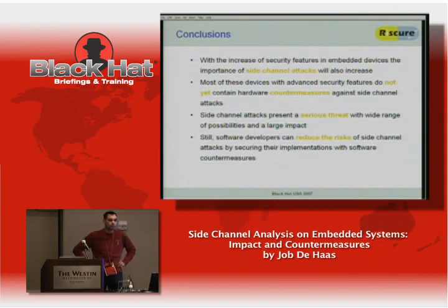Are these techniques really hard to do in an environment where you have a modern processor that has deep pipelines and hyperthreading? Does that sort of extra noise complicate the analysis? Yes, definitely, it does complicate it. But it really depends on how they're doing the implementation. If you have a software implementation, especially one that's using the external DRAM now and then for critical data, you'll see a huge signal in a chip.